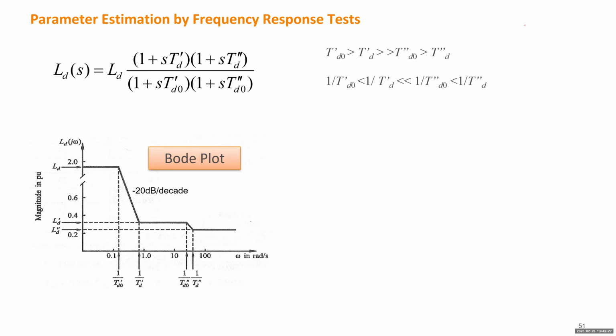But a real Bode diagram or Bode plot is not as ideal as this one. It will be very smooth. Then you have to utilize the other plot, the phase. The phase plot says when you have introduced any pole, the angle will decrease by 90 degrees. Okay, when you add a zero, it will increase by 90 degrees.